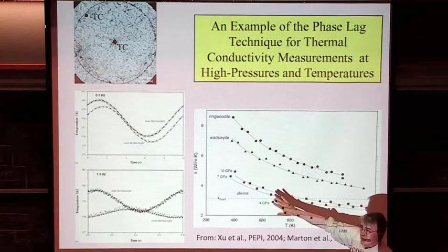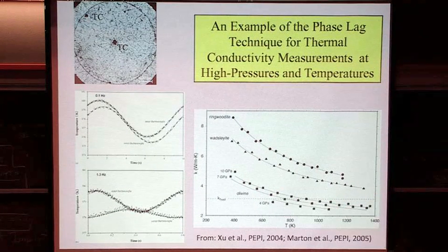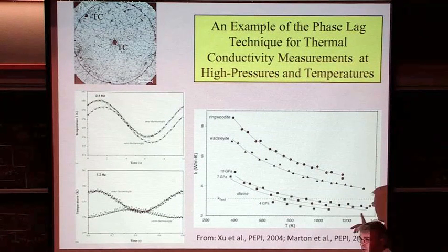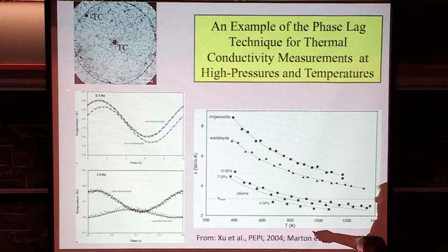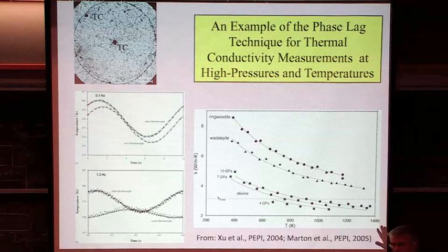Are there any experimental measurement issues, like gradients across samples or contamination? Oh, there are always some level of experimental difficulties. But I would say that the beauty of this type of experiment in terms of thermal gradients across the sample is, and I probably should have pointed this out, that the temperature variation here is actually very small. It's 4 degrees Kelvin across this entire thing. So you have basically the sample at a high temperature, and then you are modulating the temperature by just a few degrees. So temperature gradients are a much smaller problem in this instance.